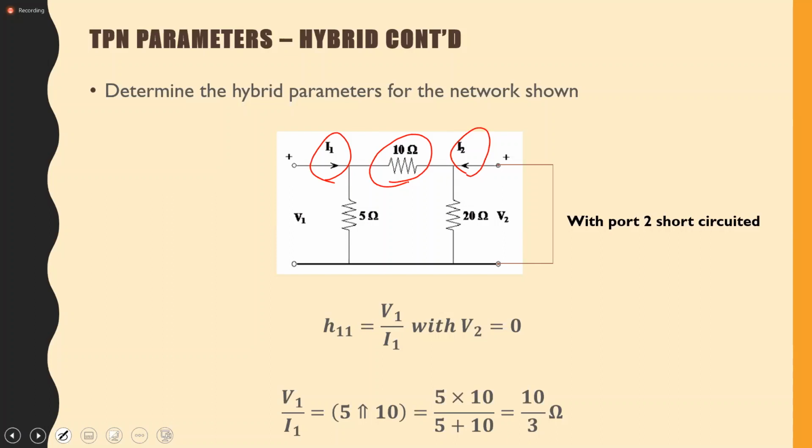Now, if that is I2, if you look at I1, if I divide I1 between the 5 ohm and the 10 ohm, then there would be a component of I1 flowing through the 10 ohm resistor. So I just use current division between the 5 and the 10 ohm resistors to find what component of I1 is going through the 10 ohm, which would be equal to the negative of I2, since we all agree that only one current is flowing through the resistor, yes?